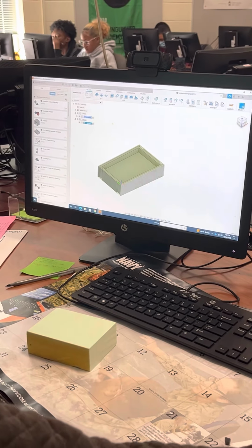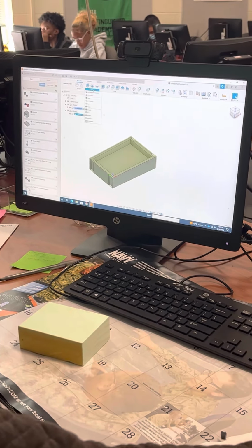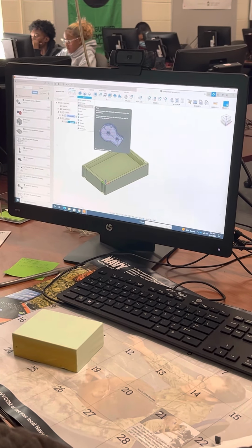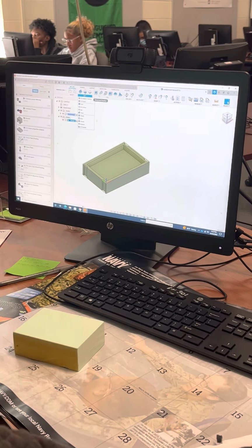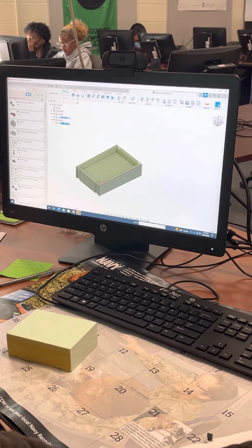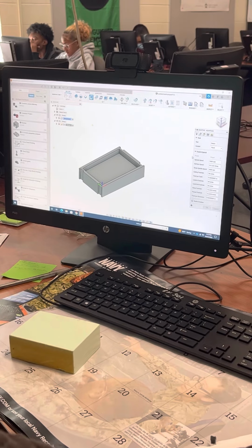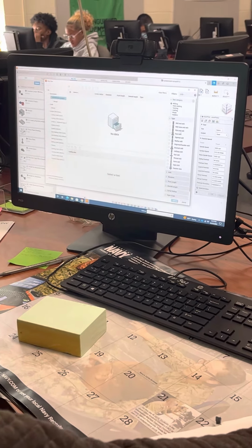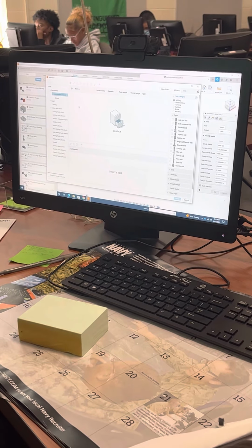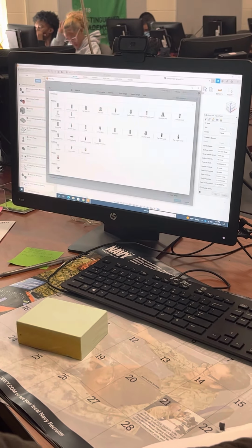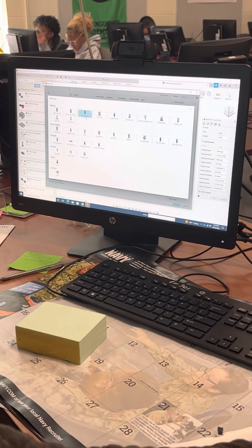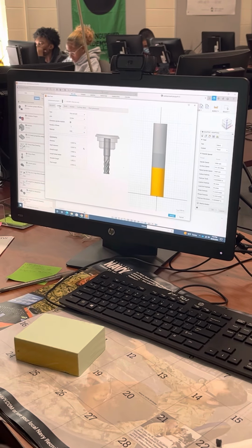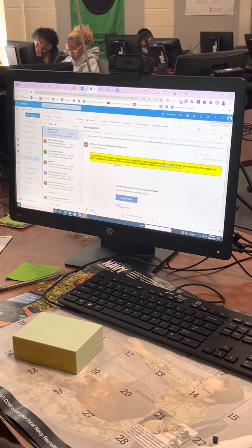So I'm going to select OK. We've got our XYZ set up. Now you can do pocket just like I did in the CAM videos, face. I'm going to try this new adaptive clearing process. I'm going to set up my tools here, select. I'm going to go to this little plus sign, and I'm going to set up my flat end mill. And I'm going to select all the same settings compared to the portfolio guide.